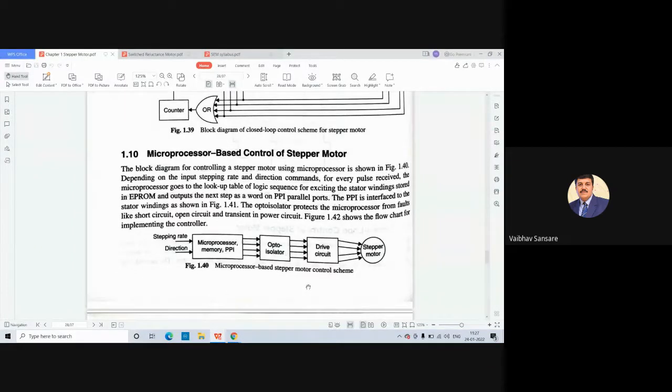Okay. So there is an isolation provided between control and power circuit. The isolation means opto isolators, that means there will be no electrical connection between control and power circuit, but whatever control signals are generated by the control circuit, that control signal passes towards the power circuit through opto devices. That means there is one opto emitter, and the second one is the opto collector or opto sensor. The opto emitter is nothing but simply your LED.